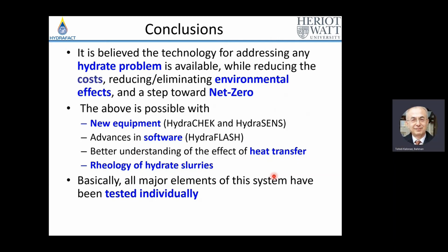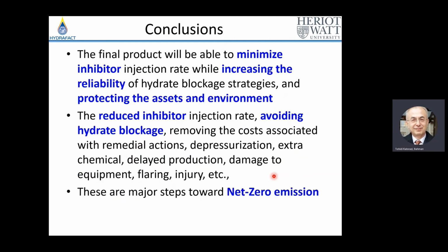Basically, all these techniques have been tested previously. We want to combine them together. The final product will be able to minimize inhibitor injection rate while increasing reliability of the hydrate prevention strategy.